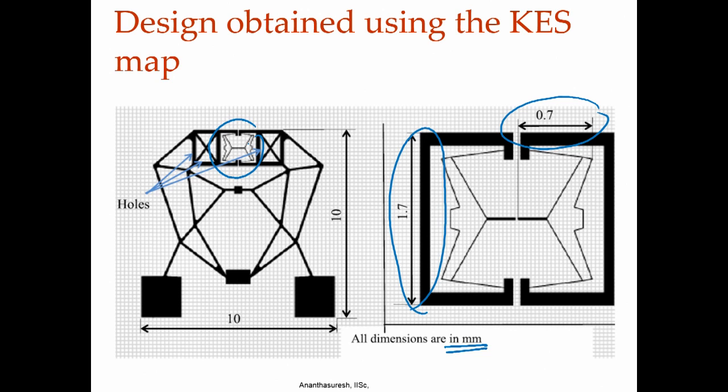So, you can design whatever size mechanism you have using this technique, you can adapt it to a smaller one, decide the size of the thing. Similar thing we have done for the cement tester mechanism, that is much bigger, much more force. We can actually estimate what should be the size, or where manufacturing limits are, we can say what is the in plane width, thickness and so forth.